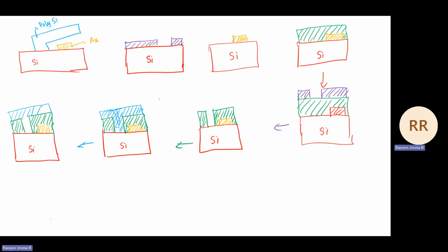So this is polysilicon. Blue color is polysilicon. In order to etch polysilicon, we need to protect this much region with PR. We need this kind of shape for the cantilever, right? So we can protect this much, and the other region we can etch.